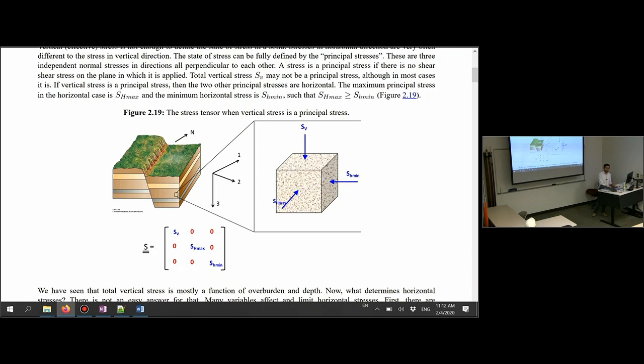And we're going to see also that that's very important for geomechanics. Don't worry about this matrix right now. We'll talk about that later on. What I want you to remember from now is that at any point in the subsurface, we're going to have three stresses, three directions associated to those stresses, and one pore pressure. So we have 7 unknowns that we need to figure out before we think about a particular problem.